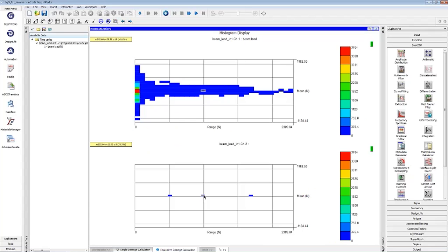Here you can see I've got 3 of these at an amplitude of 500, or a range of 1,000. And then I have 5 of the smaller cycles that I created at an amplitude of about 250, or a range of 500. Okay, so as I build this block cycle, I'm getting a more accurate representation of the actual loading here. You can see I've got some number of cycles here on the lower end, some number of medium cycles, and then one of the larger cycles.